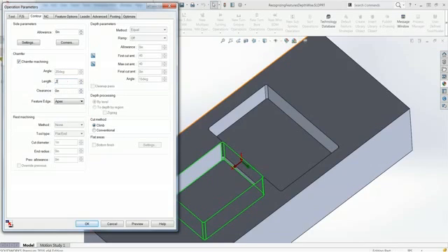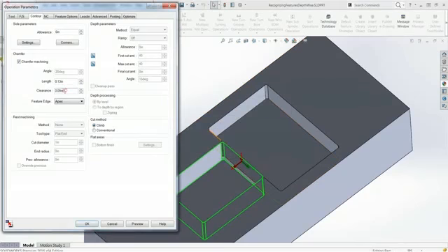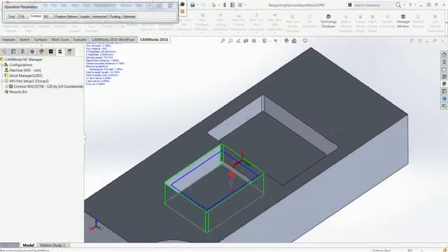Then it gives you a suggestion or like a limit. So let's just say I put in a 1/4 inch, and that's actually fairly large. And then if I want, I can do the same on the clearance. So let's say I put in 3 inches on the clearance as well. It's going to give me that same message, and then you'll notice that it gives me a clearance that matches that length. So what it's actually doing is eliminating the manual calculations that you had to do to enter your chamfer machining sizes. So it'll give you suggestions within that window. And then I can preview that, and there's my new chamfer.